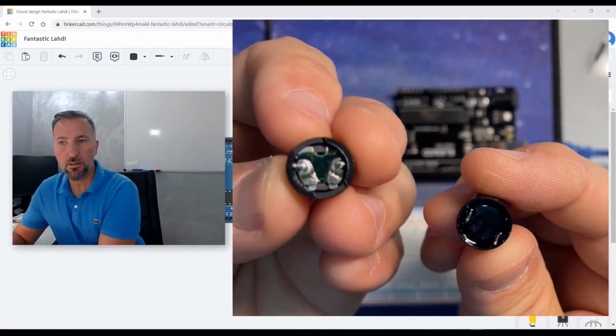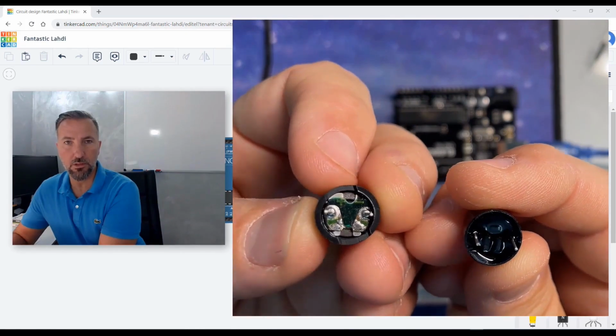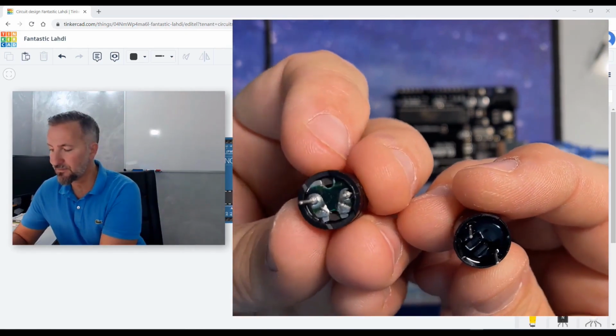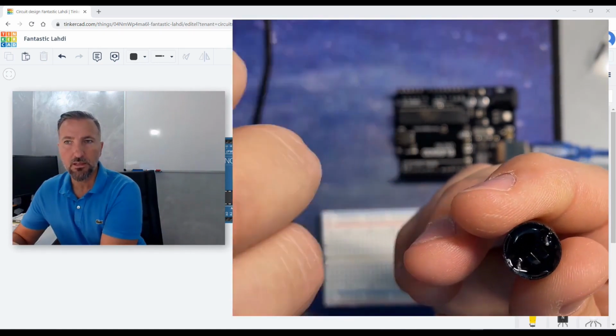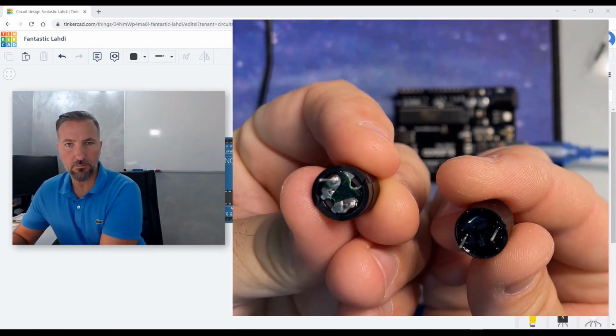The passive one is capable of being powered here with a square wave function with variable frequency, and therefore the sound emitted has a different frequency. So to emit different sounds, it will be enough to use a basic Arduino function called tone, passing it the frequency value, and the small device will emit that frequency.